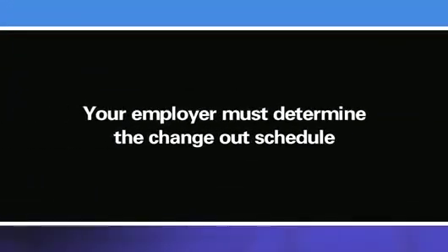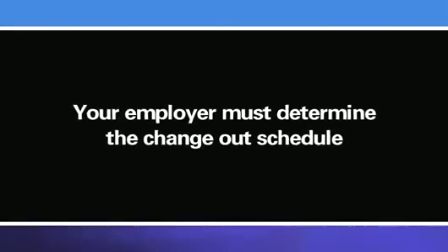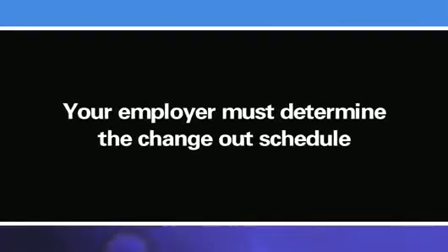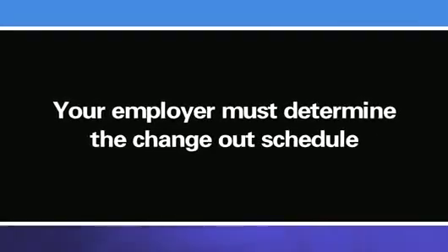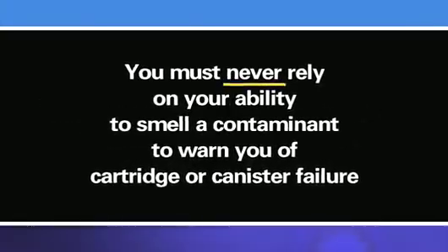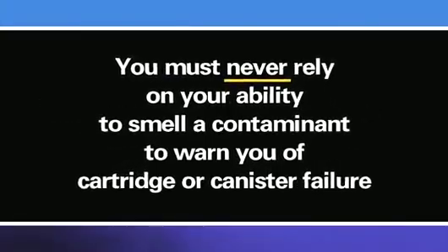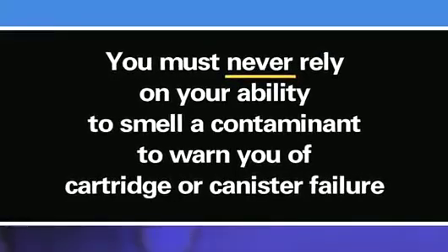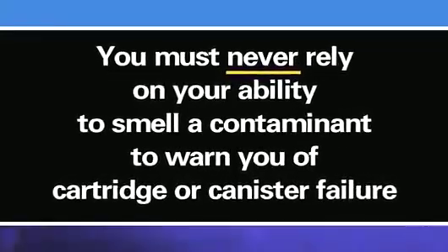This schedule for replacing worn-out cartridges or canisters is known as a changeout schedule. Your employer is responsible for providing this information to you. Remember, you must never rely on your ability to smell a contaminant to warn you of cartridge or canister failure.